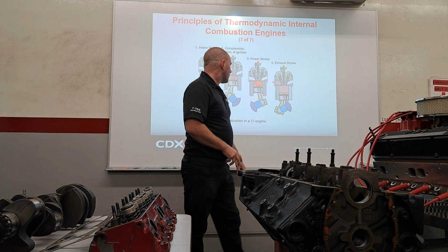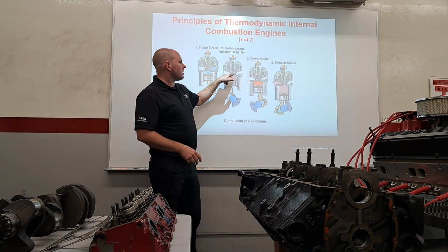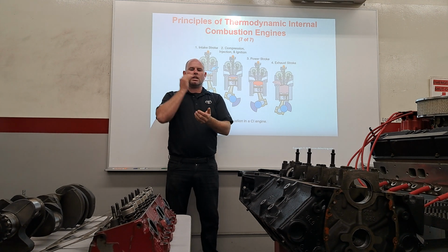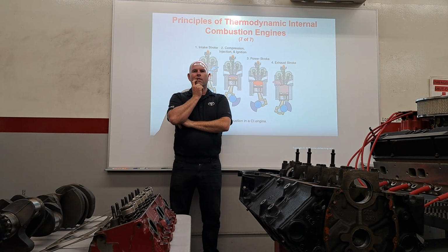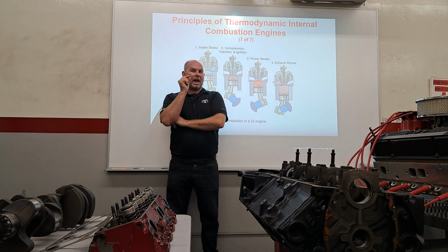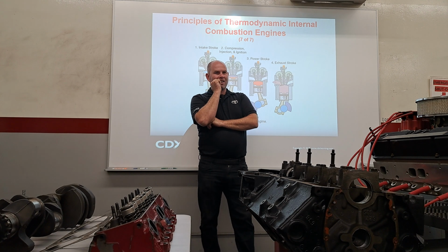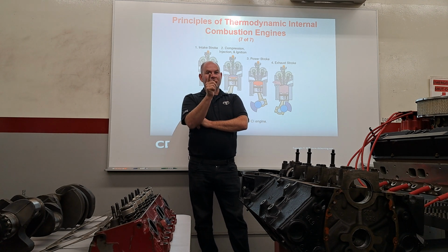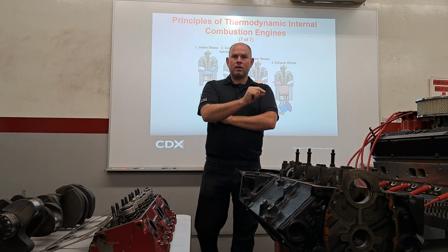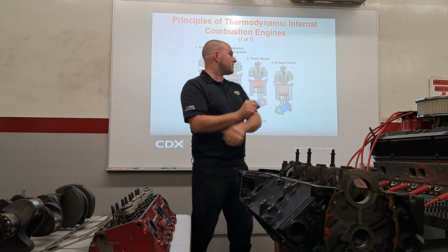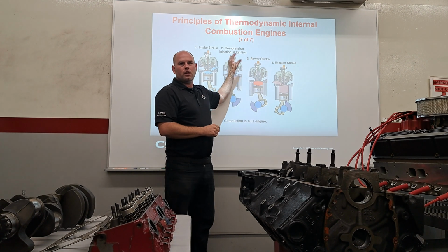Cool, but how did we start the combustion cycle in a diesel? Tell me back. What initiated the combustion? Compression. True, but at what precise moment did it start to burn? How do we control that? When you inject it. Exactly. We control timing of a diesel by the fuel. So the diesels are funny. Basically fuel calls the shot. The fuel's in control of everything.